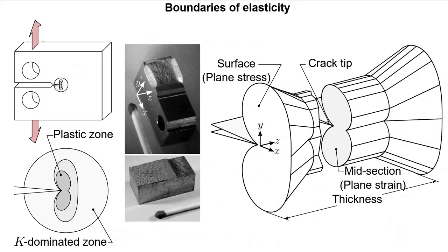The cause for this type of behavior is down to how plasticity can affect the test results. Even though the crack goes through the entirety of the specimen, and it might seem as though it might behave uniformly all the way through, it doesn't. This is because the crack is constrained differently by the amount of material that surrounds it. At the center, there is more material to carry stress, but on the periphery, there isn't any.